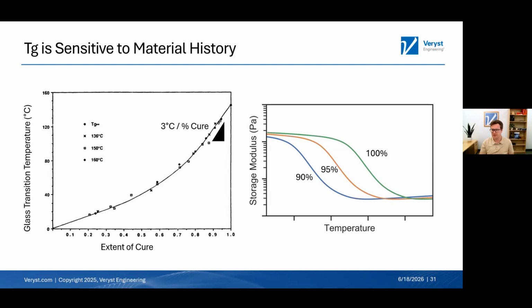So the answer is that both can be useful, but if you can use the TG, it's going to be much more extrapolatable to other parameters. That may or may not be provided by your supplier. They may only provide the HDT because it's a more straightforward test or more consistent, depending on their setup. So that's the distinction between those two things.